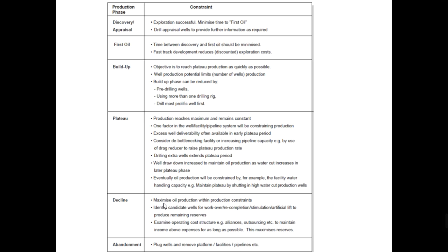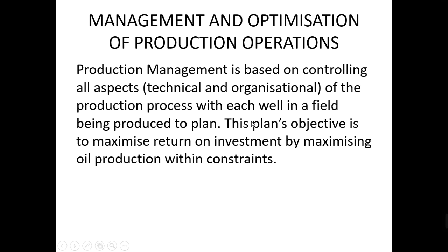And in the decline phase, you have to manage the water production or gas production, or maybe we have to look for workover operations, recompletion, stimulation, artificial lift, and so on. In the abandonment, we just close the well and remove all the facilities. So again, the plateau, where we drill more wells, and the decline, where we look for workover and recompletion because we want to manage the production, are important in this case.